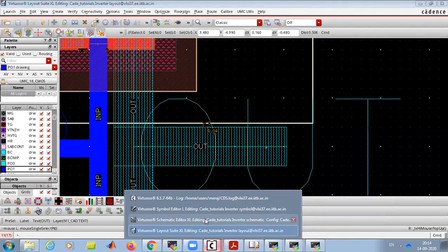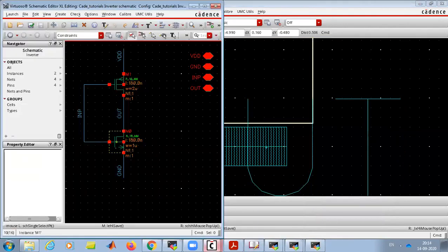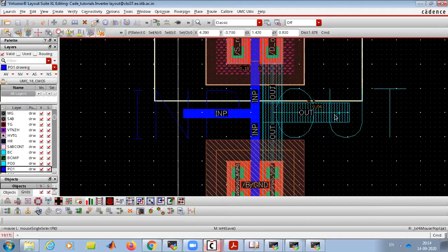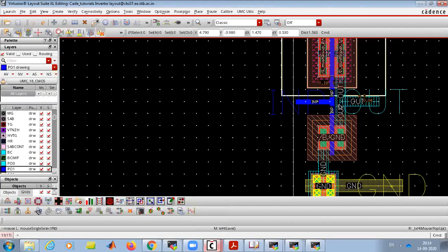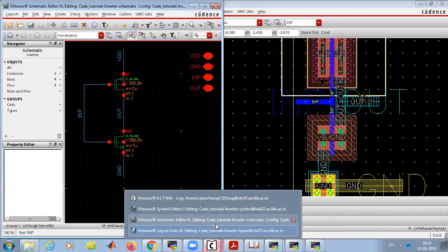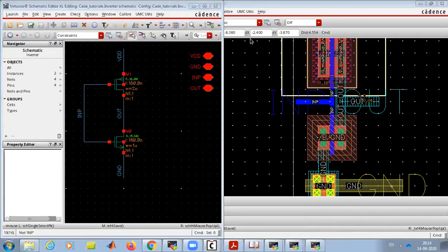schematic diagram, if we see, we have this transistor only, and you can see these nets are ideal connections. Now what will happen if in our case we have used poly to connect the two gates? It will have its own resistance. It will be very small but it will be there. So in very high speed circuits, these parasitics will just limit our design, so we need to take care of that, and we learn how we can estimate what the parasitics are in this PEX analysis.